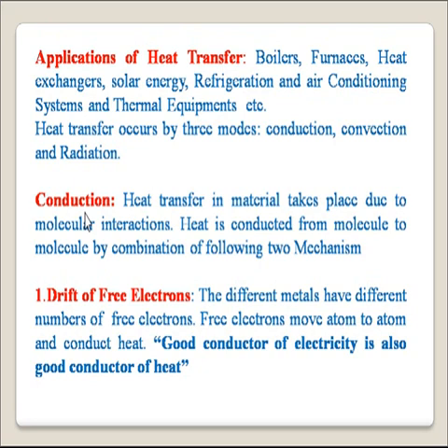In conduction, heat transfer in material takes place due to molecular interactions. Heat is conducted from molecule to molecule by a combination of the following two mechanisms. Let us consider a metal rod inserted in a furnace or fire. Then the other end of the metal rod also gets heated, and in the metal rod the heat transfer is purely due to conduction mode. The conduction takes place by two mechanisms: the drift of free electrons and lattice vibration.